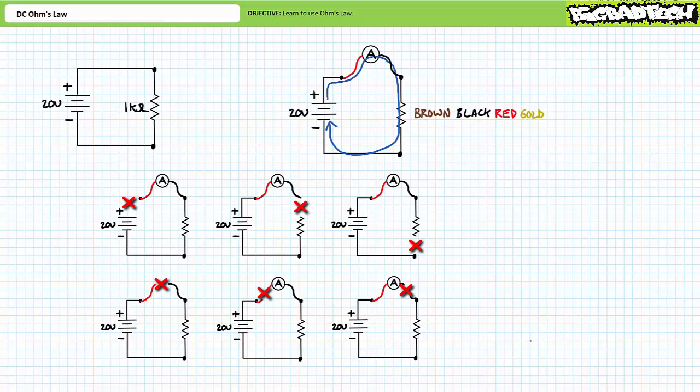As some general advice to aspiring technicians, I will be so bold as to proclaim that fully 99% of all electrical problems you will ever encounter in the field are the result of open circuits. Either some wire wasn't properly tightened on a screw terminal, or it was properly tightened and shook loose, got pulled out, or got cut.